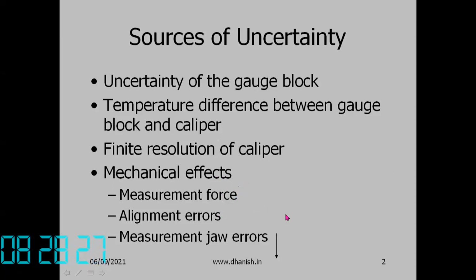So it should be a constant measuring force. That's why in the micrometer we have a ratchet mechanism to make the constant measuring force. But in the Vernier, we don't have any ratchet mechanism or a force controlling mechanism. So this is always a source of variability and depends on the person, how much force he applies. Only with practice you will learn how to apply the right force so that you get the right measurement. So that is one problem with online lab.